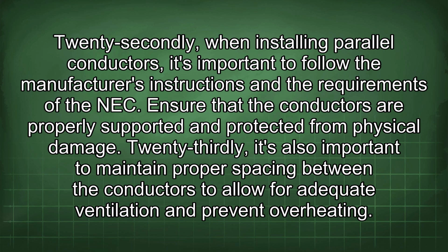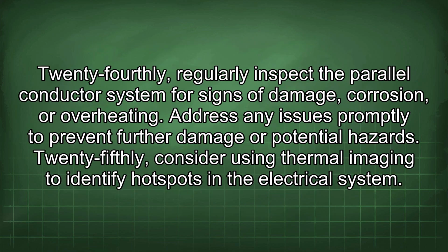Ensure that the conductors are properly supported and protected from physical damage. 23rdly, it's also important to maintain proper spacing between the conductors to allow for adequate ventilation and prevent overheating. 24thly, regularly inspect the parallel conductor system for signs of damage, corrosion, or overheating. Address any issues promptly to prevent further damage or potential hazards.